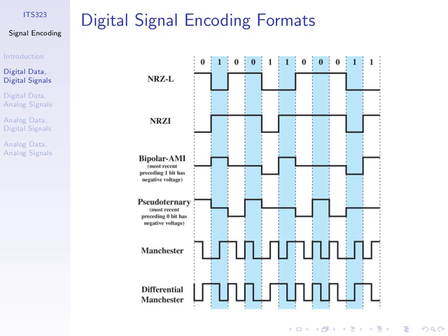We cannot do that from this encoding scheme. We don't know whether this is exactly what was transmitted or not. Here, we know this is not what was transmitted, because the transmitter would never transmit high, low, low. So some encoding schemes have inbuilt error detection, which is useful.